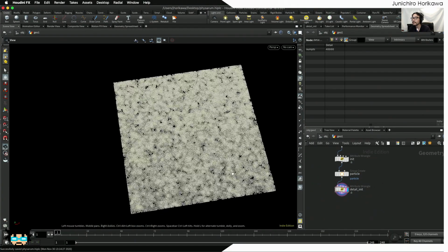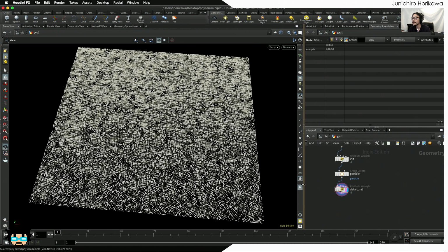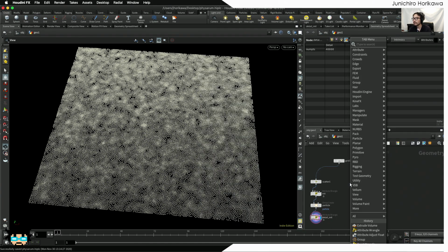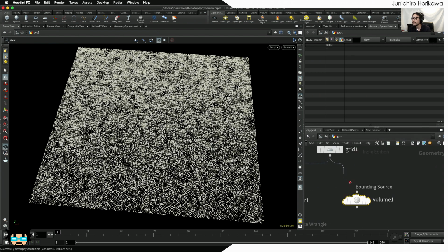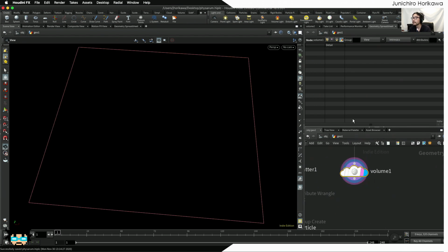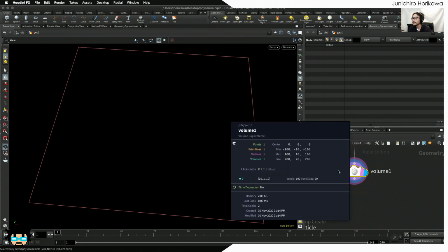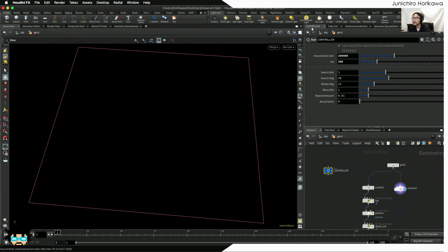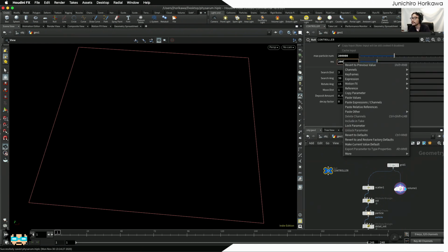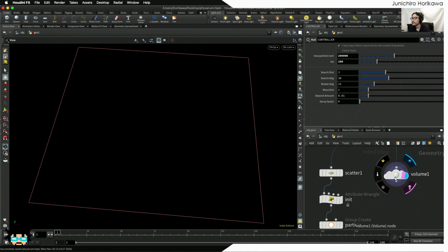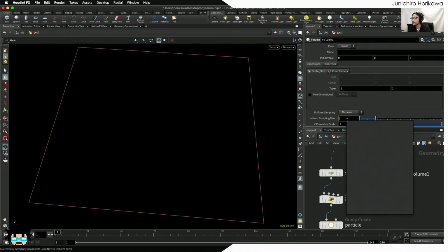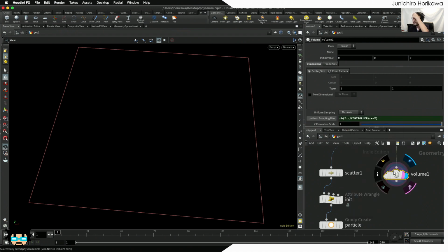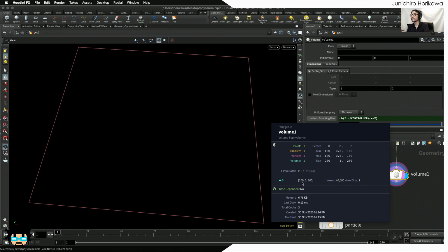Let's also create a grid information for the trail map with a volume. To do that, first I'm going to connect the volume node to this plane, and currently the resolution is 10 by 10, so I want to make the resolution the same as the width and height, so let's use this value. So copy this one and paste it right here to the uniform sampling divs, so that you'll be able to control the resolution like this.